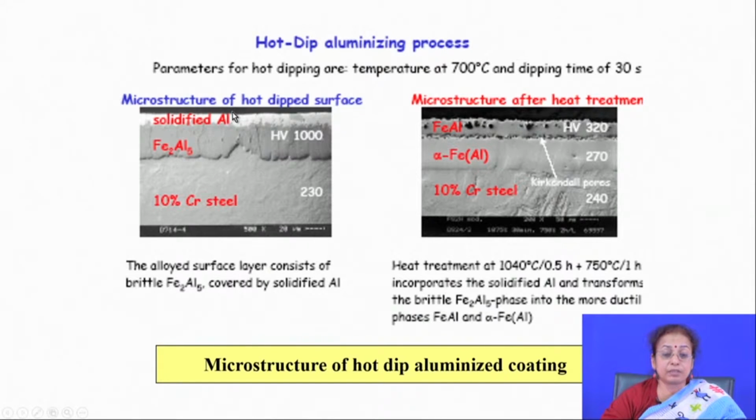On the other hand, if you talk about different types of wear, if the interface is not strong, there is also a possibility of failure of the components from the interface. So, the interface plays a very important role. Whenever you talk about coating, you should see the interface very carefully. Interfacial observation means interface microstructure, interface composition distribution, and the defect density throughout the interface from the surface towards the interface. These all play a very important role in determining the behavior of the coated material.